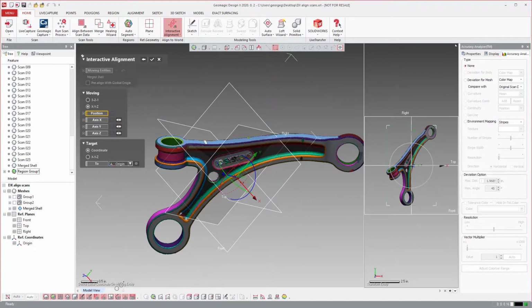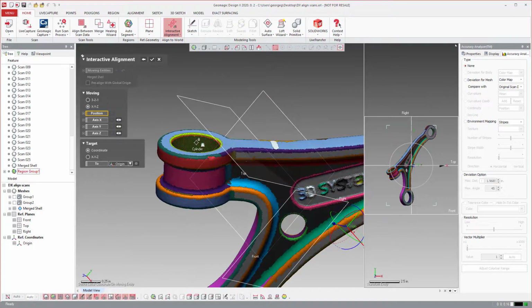This guy right here, if you look down here. So if I wanted to square up this cylinder with the y-axis of that coordinate system, how do I do that? I will show you now. In order to constrain the position, remember I said I want to put 0 right here.